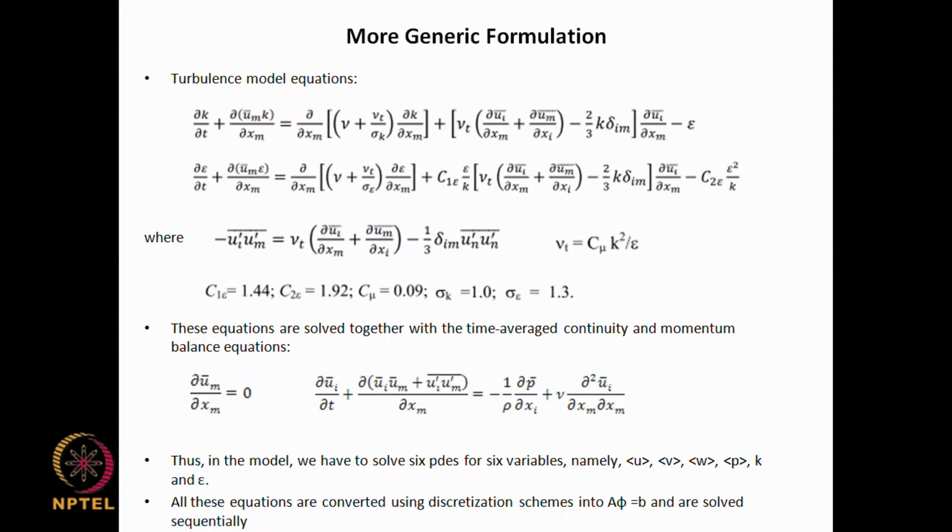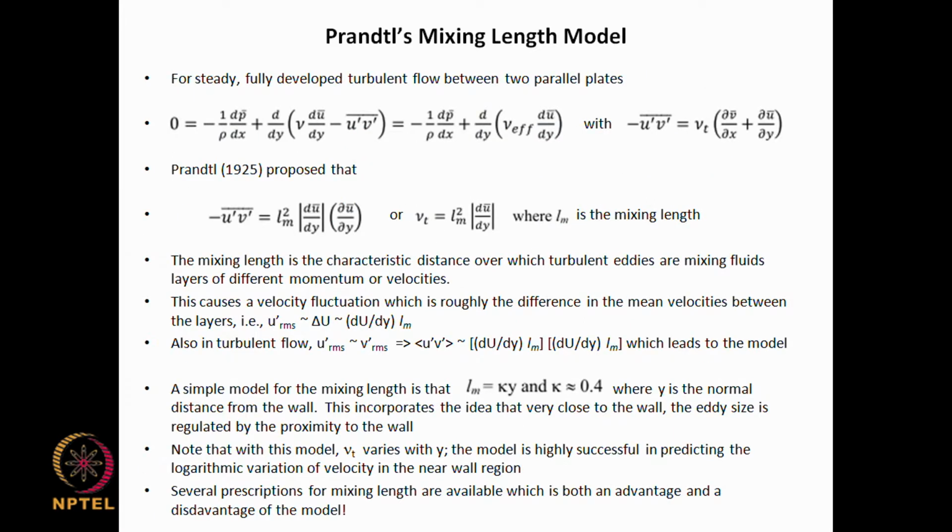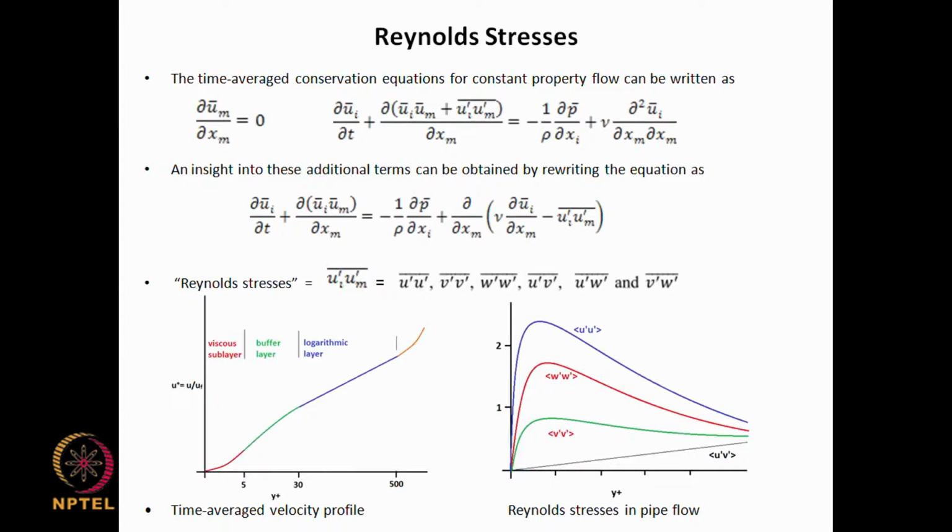And there is also another class of turbulence models in which you do not solve just for these two parameters k and epsilon, because what we have in the actual equations are the 6 Reynolds stresses. So solving only for the sum of the first 3, which is k, and not solving for anything else, and then using another variable epsilon, is considered not to be accurate enough for certain cases, especially when you have strong curvature effects.